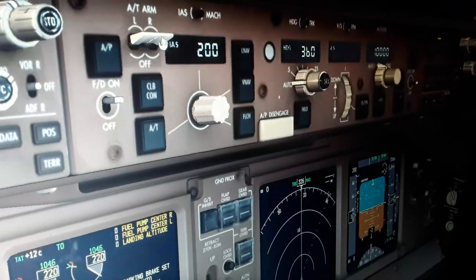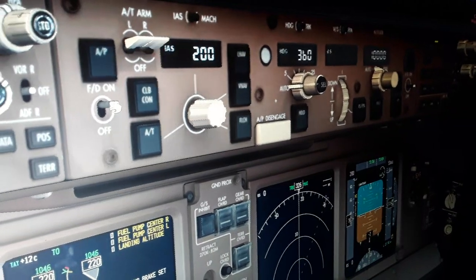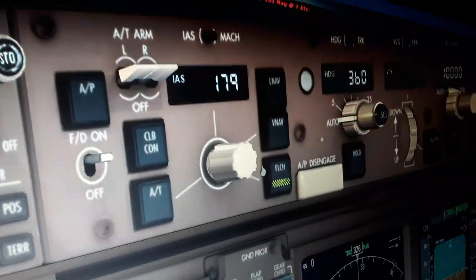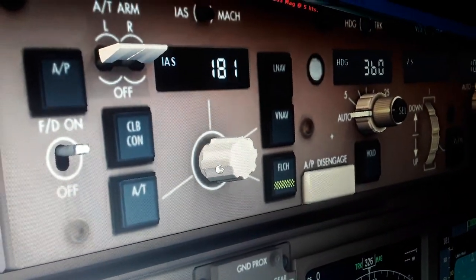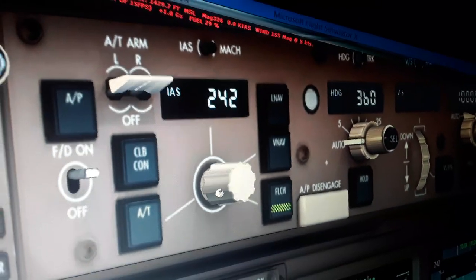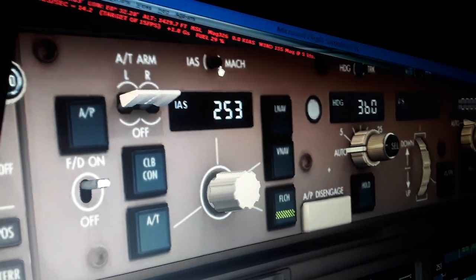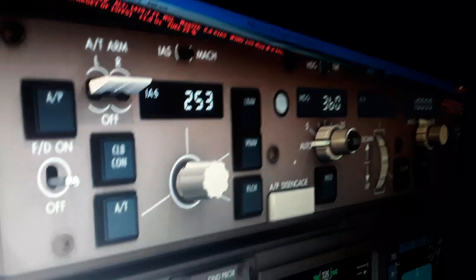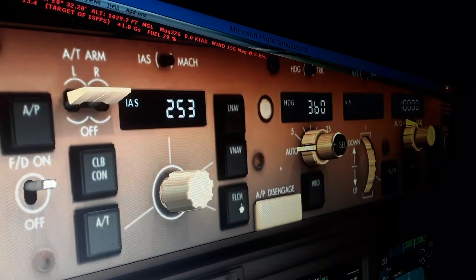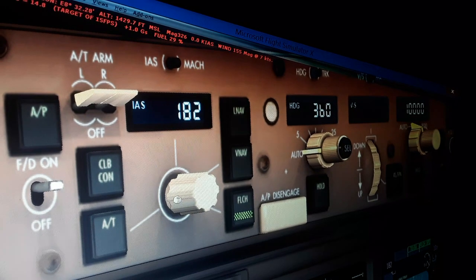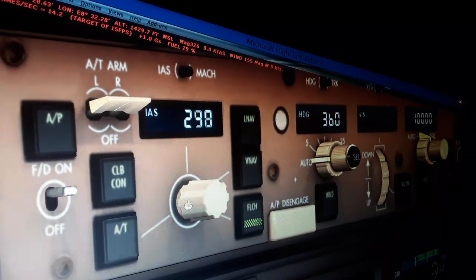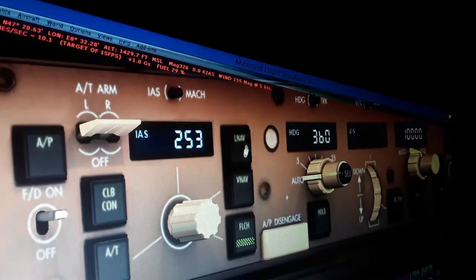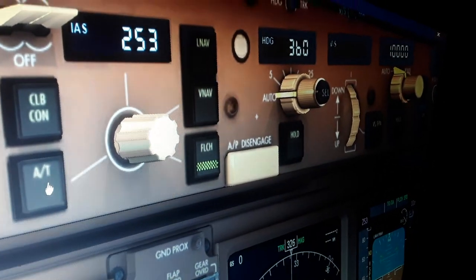You can see the auto throttle left and right here systems with the flight director on and off. The flight level change here, I can change the airspeed select, so you can see this is the press box, so I will select a higher airspeed for the aircraft to follow, and also indicated airspeed or Mach over here. So both these two are depressible. You can turn off the flight level change. You have to reset everything after turning off the flight director. The values. So you have also the climb continues, the auto throttle, the LNAV, the VNAV. All these are depressible.